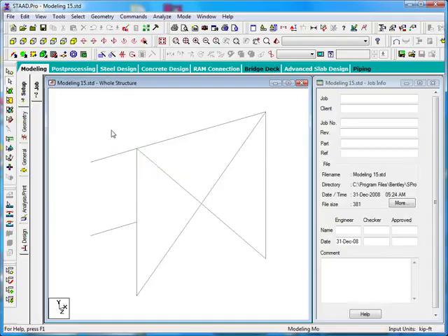Sometimes orphan nodes are created intentionally. They may serve a meaningful purpose to mark a control point or a point where another piece of a model will be inserted at a future date. They may serve as a working point or a center point for a generation of circular elements. And so there's no problem with working with orphan nodes during the modeling process.